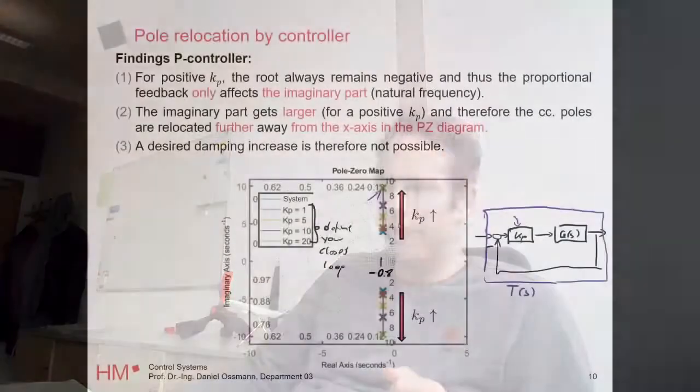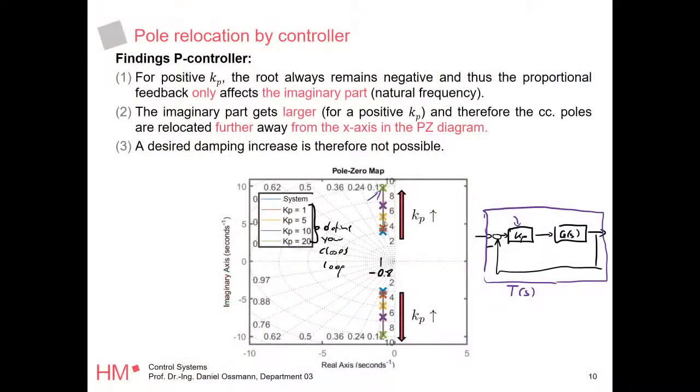Now, if you understand that, that's good. Now you do it for all different controller gains you can imagine, and what you end up with is a root locus line. This is the gray line here, and actually the gray line continues to go outwards for that example.